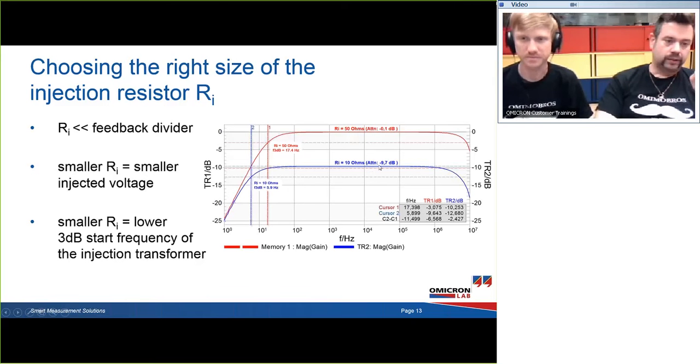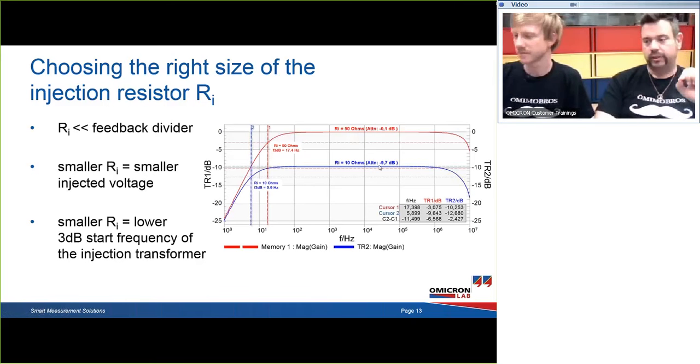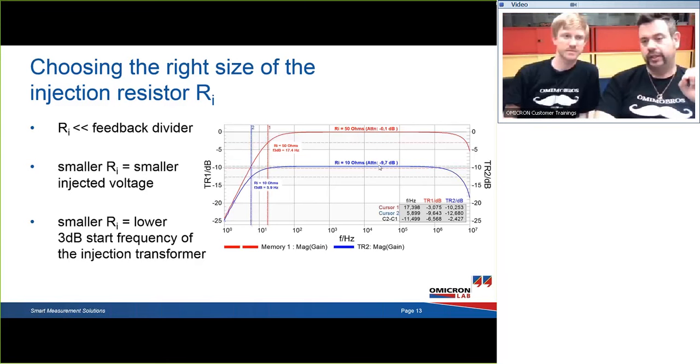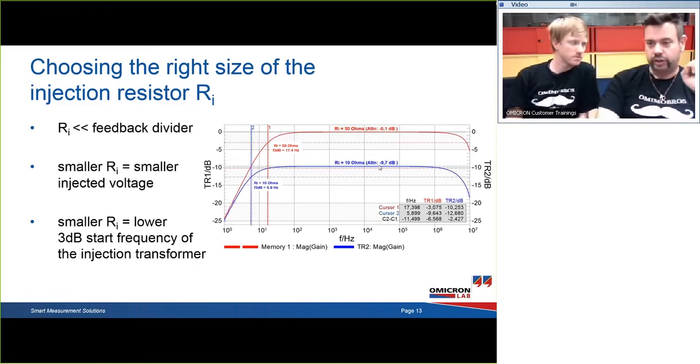We will find out that typically for the measurement of loop stability, it's important to use small levels. Small levels where our signals always remain in sinus shape. There is no clipping, there are no harmonics, so that in the end we can make a small signal measurement.